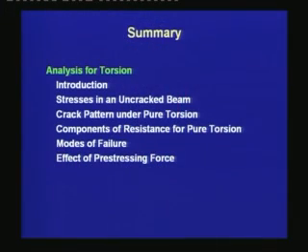There was another concept which we had studied, which is the thin wall tube, which comes from this observation of the resistance of torsion in the peripheral region of the member. Next, we moved on to understand the components of resistance for pure torsion. The torsion is resisted both by the concrete and the steel bars. The concrete resists the torsion by compression in the struts, and the steel bars are in tension which hold